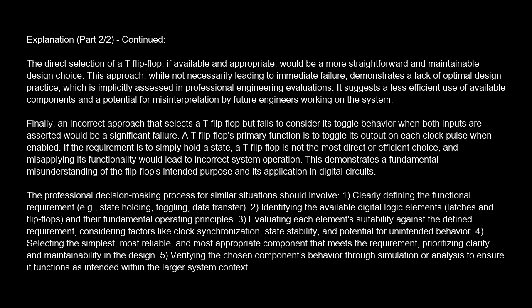Finally, an incorrect approach that selects a T flip-flop but fails to consider its toggle behavior when both inputs are asserted would be a significant failure. A T flip-flop's primary function is to toggle its output on each clock pulse when enabled. If the requirement is to simply hold a state, a T flip-flop is not the most direct or efficient choice, and misapplying its functionality would lead to incorrect system operation. This demonstrates a fundamental misunderstanding of the flip-flop's intended purpose and its application in digital circuits.